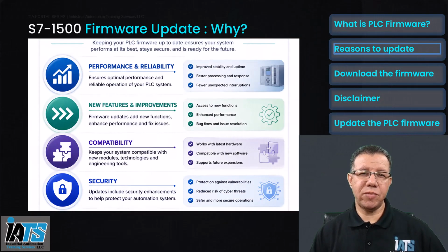The first reason to update the S7-1500 firmware is to ensure compatibility with your current TIA Portal version, especially if the CPU is an older model. Otherwise, you won't be able to run your program using your current TIA Portal. Updating the firmware also fixes the discovered bugs, improves system stability, and enhances protection against security vulnerabilities. It also adds support for recent hardware and new system features.